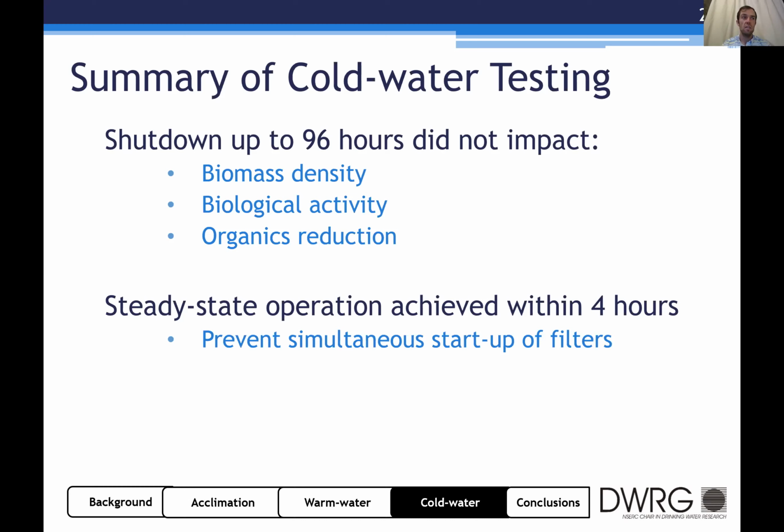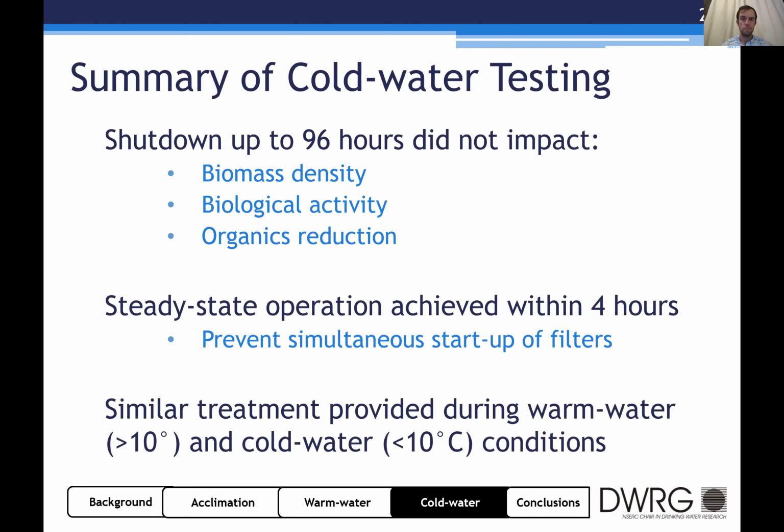And future studies that we're going to look at will evaluate filter to waste to see how long of a period that requires to reach steady state. And ultimately, similar treatment was provided during warm and cold water conditions, and that likely plays into the fact that they can optimize coag dose to improve physical and chemical removal and combine that with biological treatment.